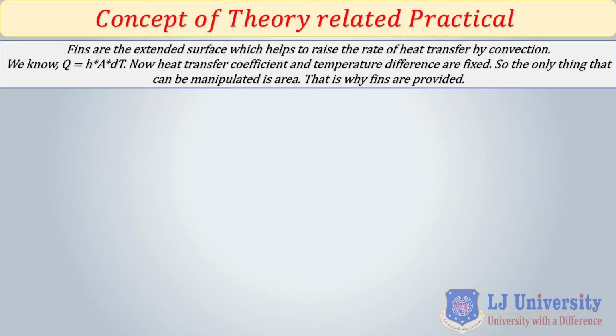Some of you might have seen fins attached in automobile engines. Why are fins attached over here? Because sometimes the engine gets heated, and there is a possibility that it will cause failure of the engine. So that's why some additional surface is provided to the engine to increase the rate of heat transfer, so that the engine will stay within a limit. So these extended surfaces, or additional surfaces which are attached to a device or a wall or a material, are known as fins, to increase the rate of heat transfer.